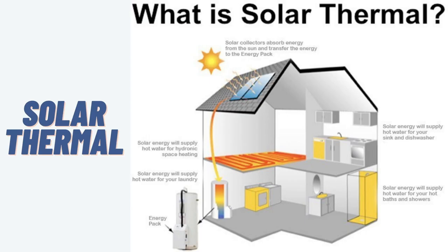Solar thermal energy is harvested using a panel to absorb the sun's rays, which are used to warm a fluid or, in some cases, the air. The fluid can simply be water or, in areas at risk of freezing temperatures, a glycol mixture similar to that used in car radiators. The warmed water is circulated, usually by a controller and generally through a heat exchanger. It can be used as a part of heating or hot water system.